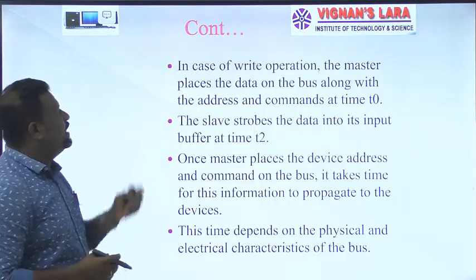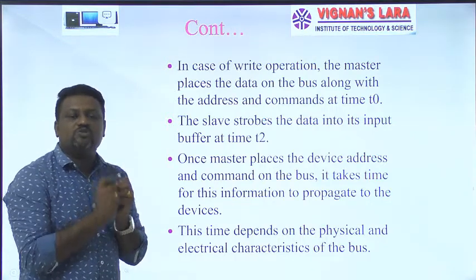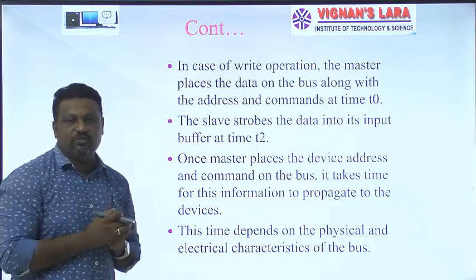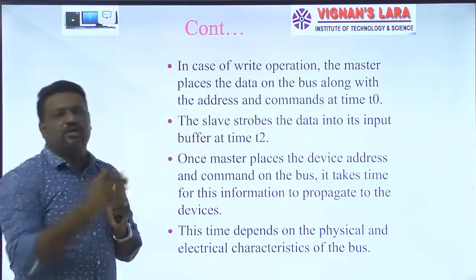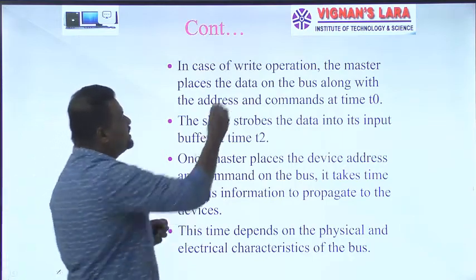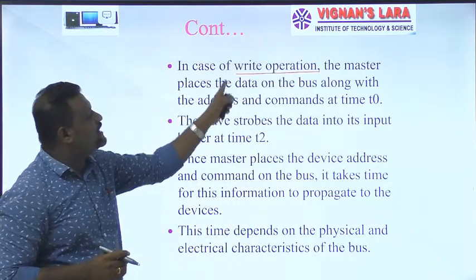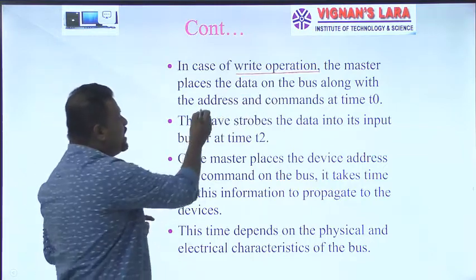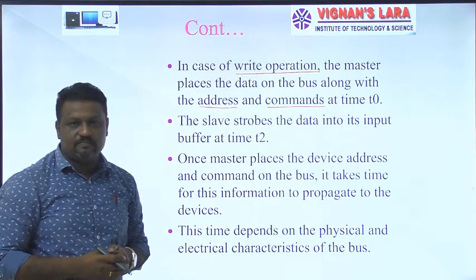In the case of a write operation, if my operation is write, that means the master is to send something to a device which is connected to the same bus. It means your master wants to send something to a slave. That operation we consider a write operation. The master places the data on the bus along with the address and the commands at the time instant T0.